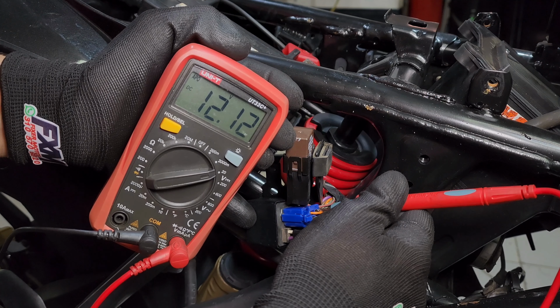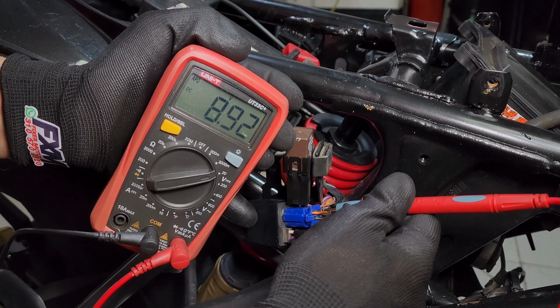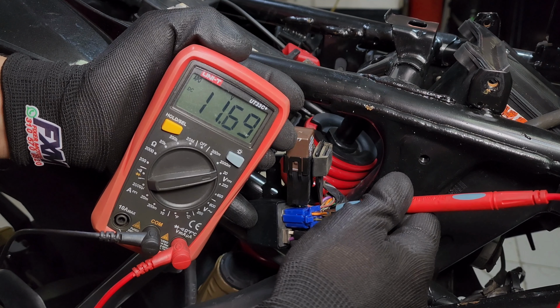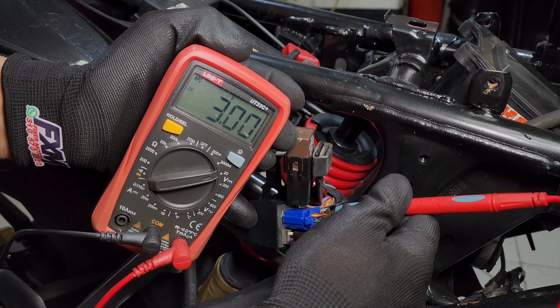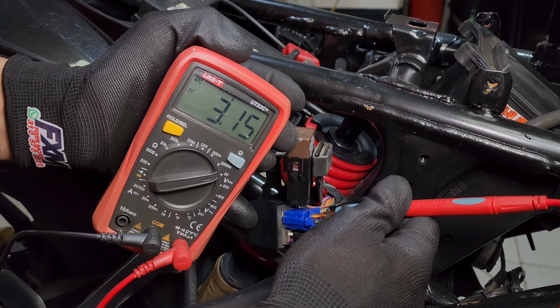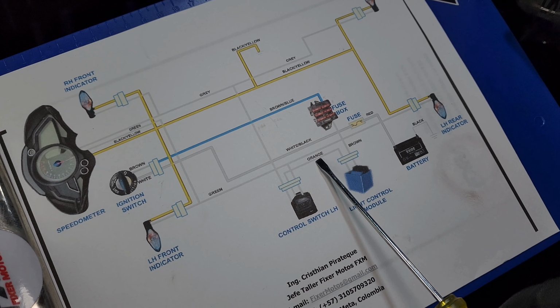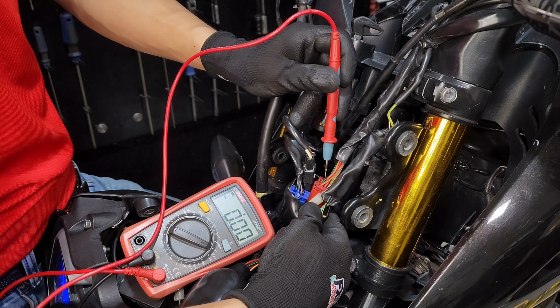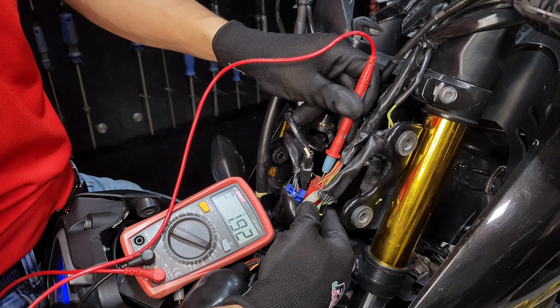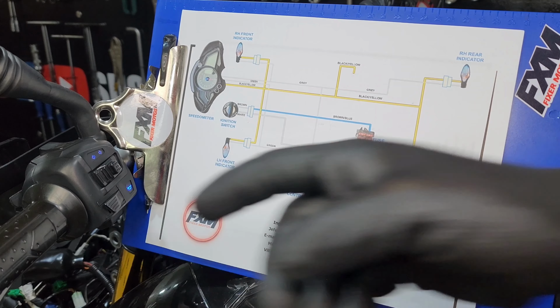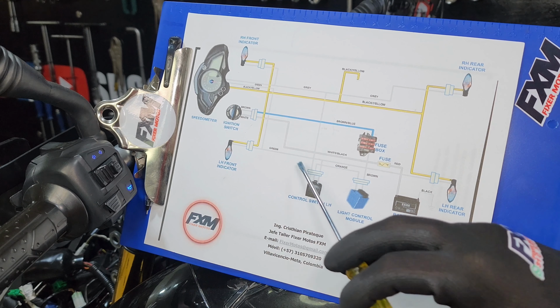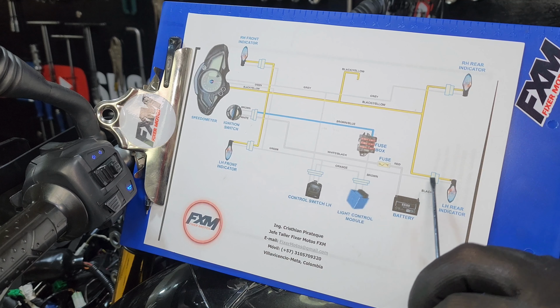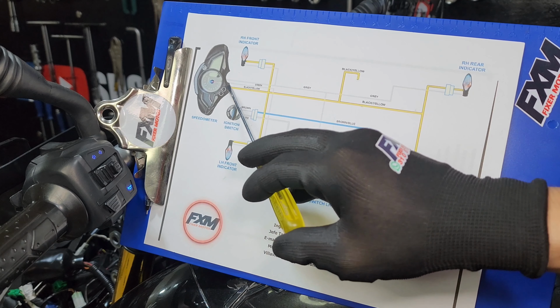It arrives through the brown cable and goes out through the orange cable. And as you can see, it is internally because it is already performing its flashing function. And this orange cable goes to the left command, to the directional button, which is in the command connector. And when activating the command to the left, this orange cable exits through the green cable for the 2 turn signals and the instrument panel.